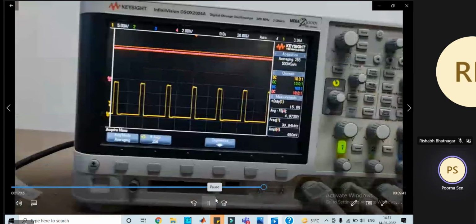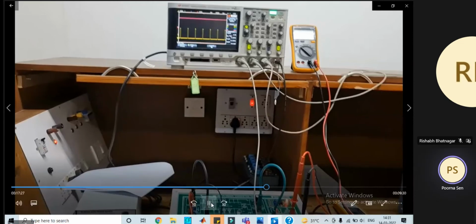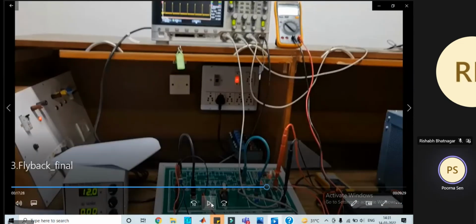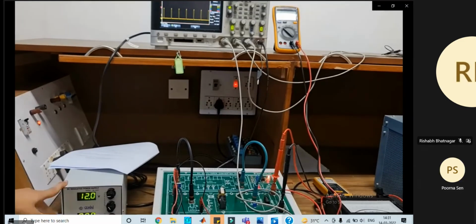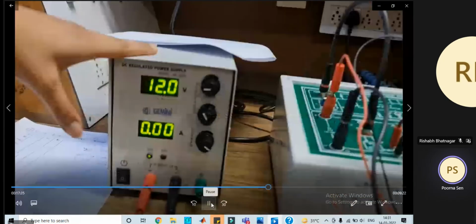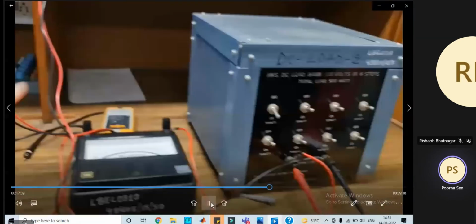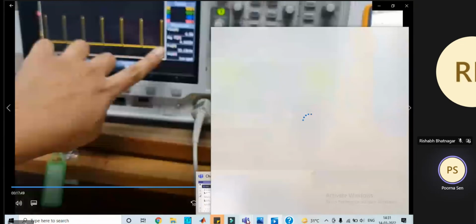Input voltage 18 volts, duty 15.8%, output voltage 4.975. The previous table was for input voltage variation, where the load was fixed at 80 milliampere, and the input voltage was varied from 6 volt to 18 volts. Now in the second table, we will keep the input voltage fixed at 12 volts and we'll vary the load, and we'll see how the output current or load current varies, the duty ratio and the output voltage.